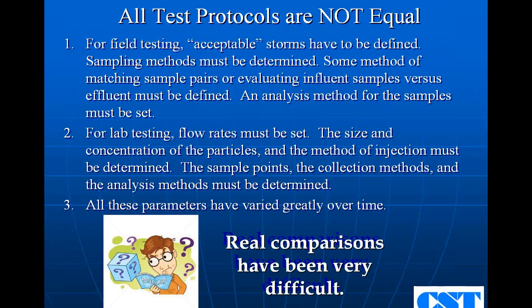And then the method of injection. Are you pouring in dry sand? How do you make sure it's coming in at 200 milligrams per liter? Is it a wet slurry? Is it injected in the top of the pipe, the bottom of the pipe, the middle of the pipe? I mean, there are lots of things that can vary.